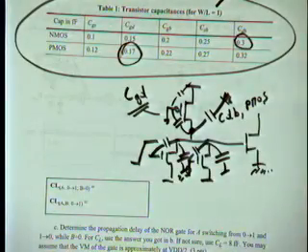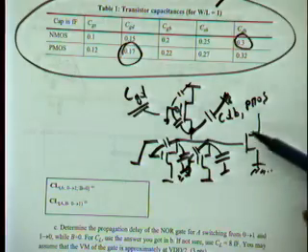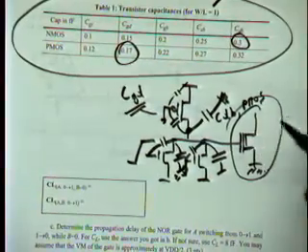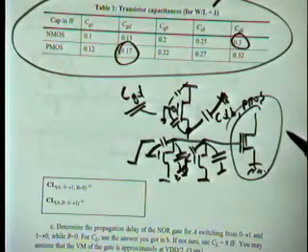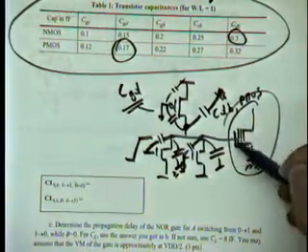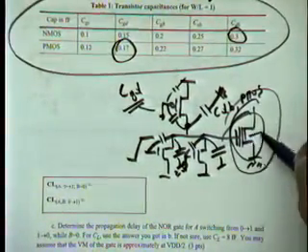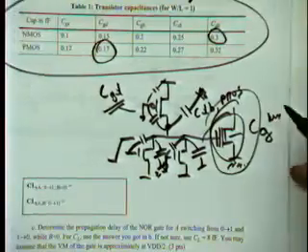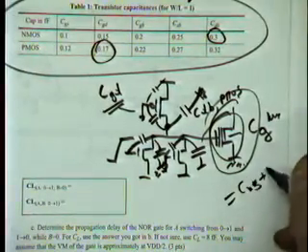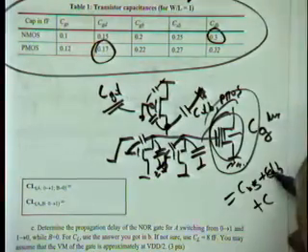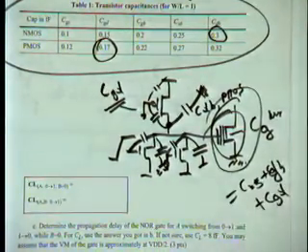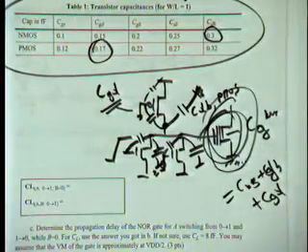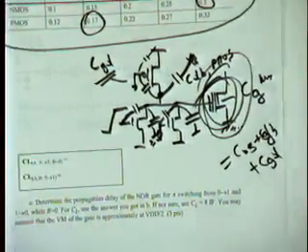That's all. What else is left is obviously the capacitance of the load device. There's an NMOS transistor here connecting only one NMOS. No PMOS in this case, like we would have in a traditional inverter. So we know the capacitance of this. This is the gate capacitance of the NMOS device. So you have C gate, the total gate capacitance of the NMOS device, which is equal to CGS plus CDB plus CGB plus CGD. You add them all together and say that's the load capacitance that's offered by this NMOS transistor here.